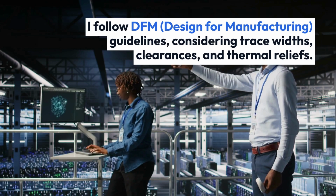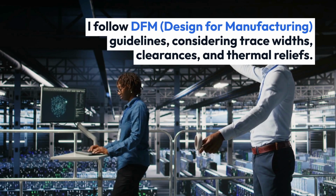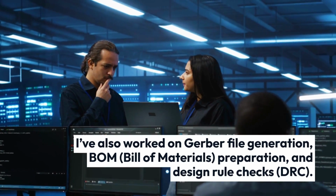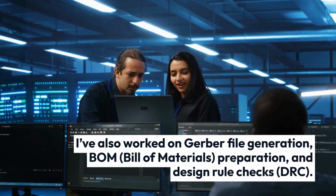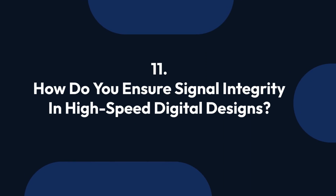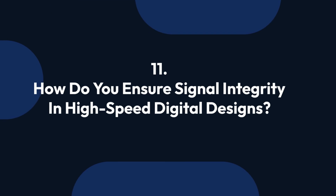I follow DFM, Design for Manufacturing, guidelines, considering trace widths, clearances, and thermal reliefs. I've also worked on Gerber file generation, BOM, Bill of Materials, preparation, and design rule checks, DRC. During prototyping, I collaborate with fabrication vendors and perform functional and electrical testing to validate the design before production. 11. How do you ensure signal integrity in high-speed digital designs?